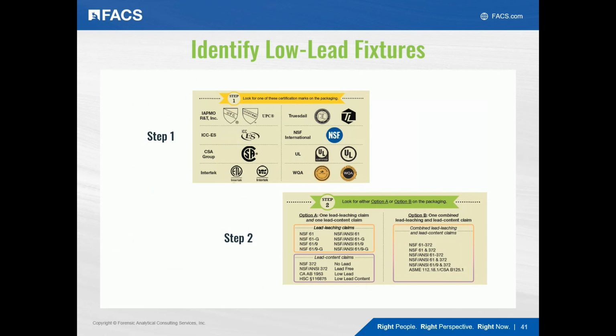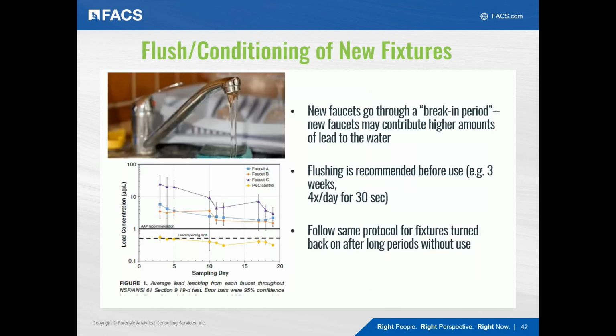Okay. And there's certain certification marks you can look for to identify low lead fixtures. The fixture needs to be certified to have both a low content of lead and also a low potential for leaching of lead. Okay, so these are two separate things, but they're both important. And be sure to flush the new fixtures after installing them. So ideally, several times a day for the first few weeks. Why is this? It's actually because new fixtures can leach higher levels of lead in the beginning during sort of a break-in period.